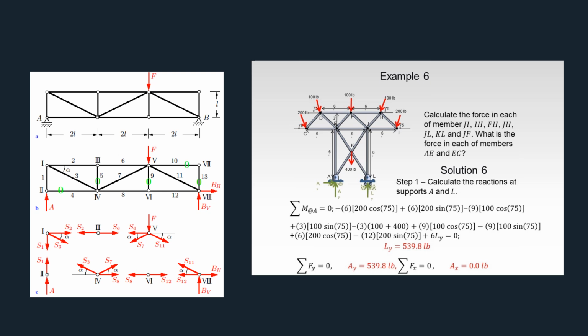I also wanted to mention one more thing: if you get a negative number, that means there are compressive forces acting on it and it's not tension. That's how you can tell the difference between tension and compression when you solve these equations.